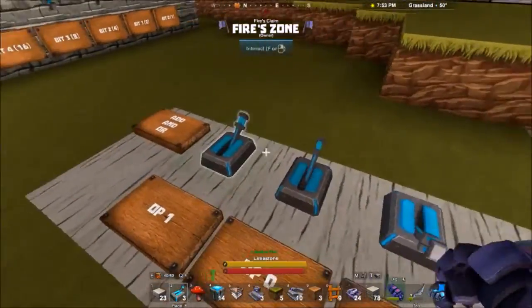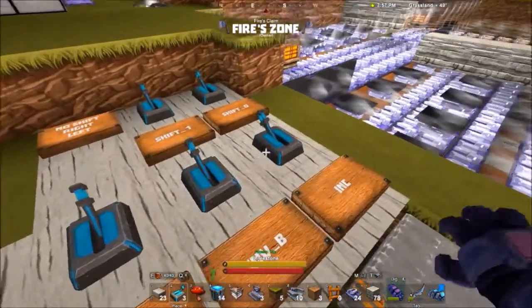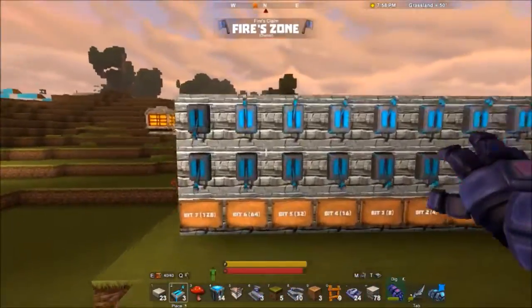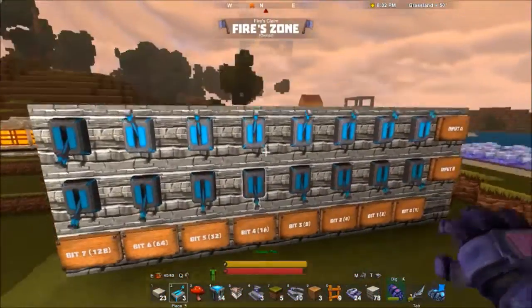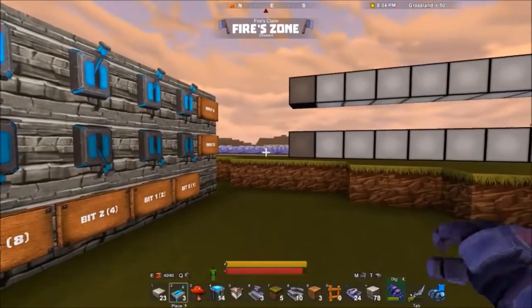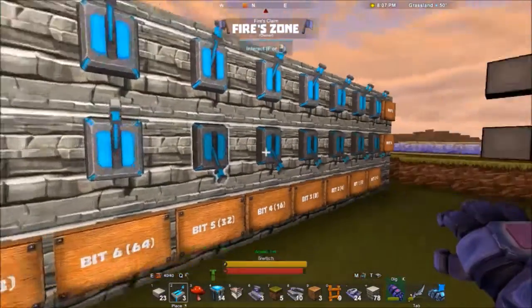So what I'm going to do, I have it on 0, both inputs are enabled, and the inverters are 0 and the increment is 0. I'm going to start generating carries first from this one all the way to the end, and see at what point the look-ahead carry adder becomes faster. So let's start from this one.